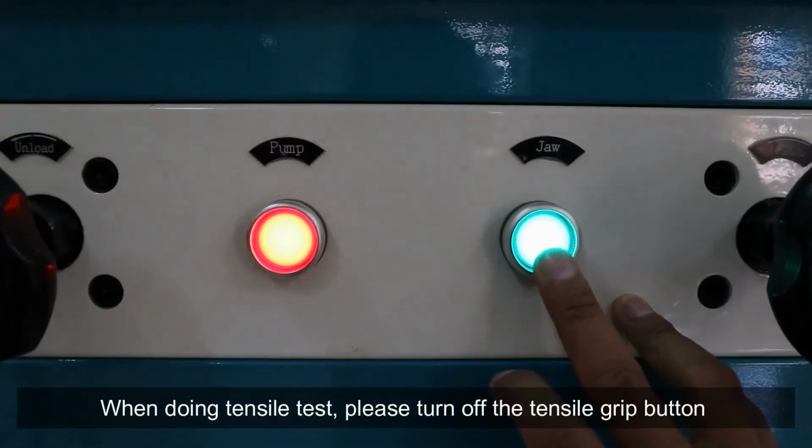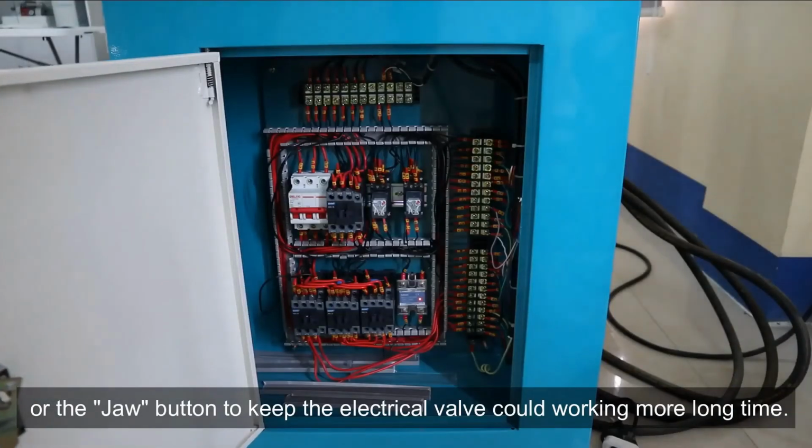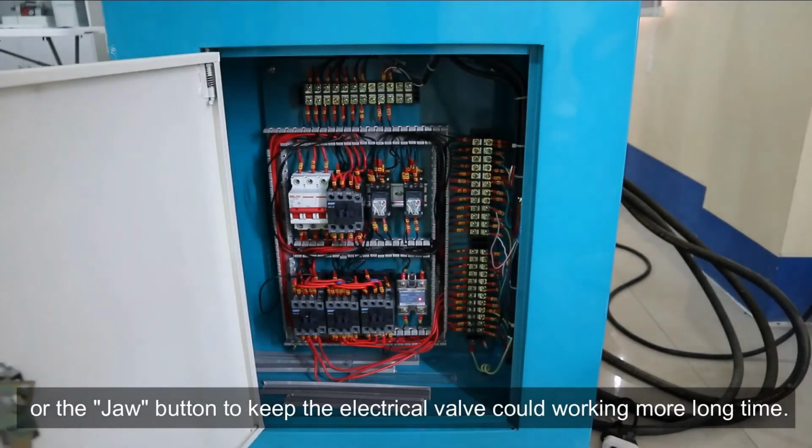When doing a tensile test, please turn off the tensile grip button or the jaw button to keep the electrical valve working well for a longer time.